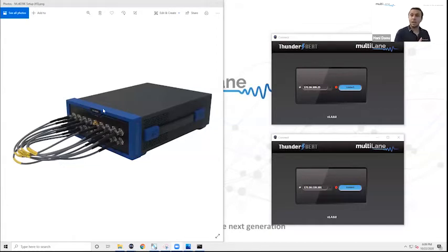Now, on the left, you will see the hardware setup, one out of two, the first hardware setup that we're going to show you today. This is our 4039E platform, and it is going to be in full electrical loopback with RF cables. Now, the 4039E has 4 channels, each one capable of 58 gigabaud. Now in PAM4, that is a full 400 gig electrical link, exactly what the industry is using to bring 400 gig, 800 gig designs to market.